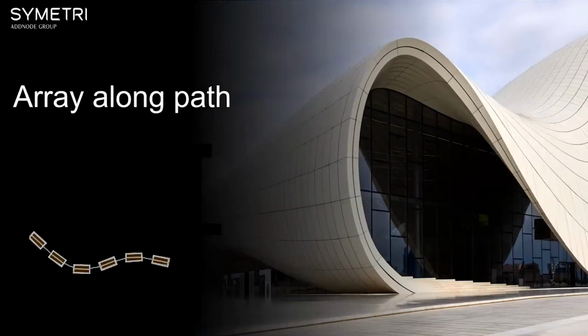And the final one is an array along path. Now what this does is this allows you to just simply draw a model line or a model curve inside Revit. You can then take a family and distribute that along a path. Okay, so nice and simple tool, but again can be really, really useful. So that's really my top 10, but of course there could be hundreds of other examples.